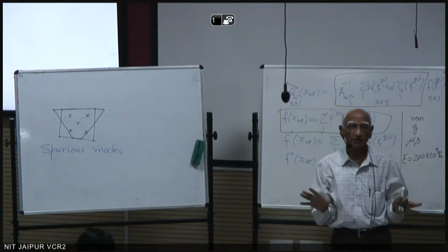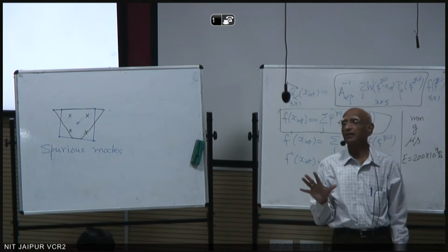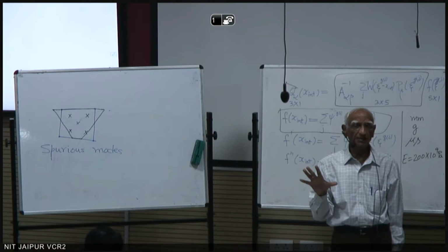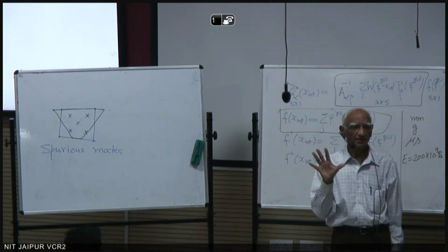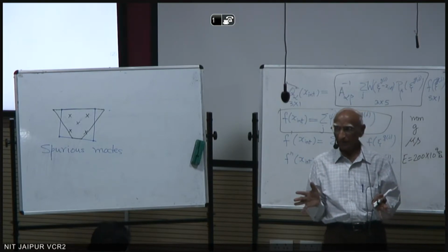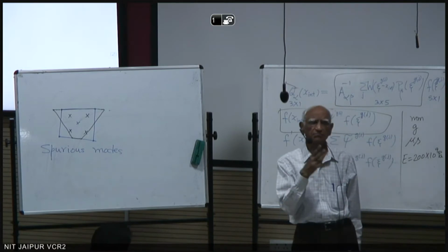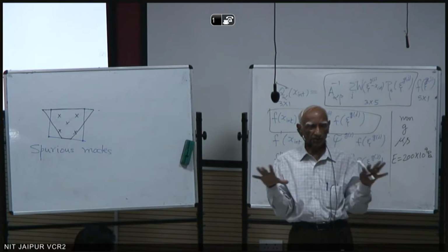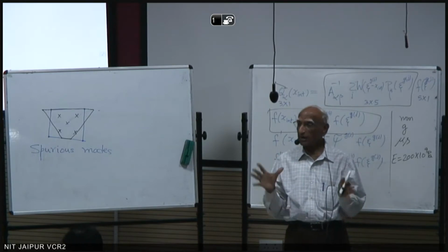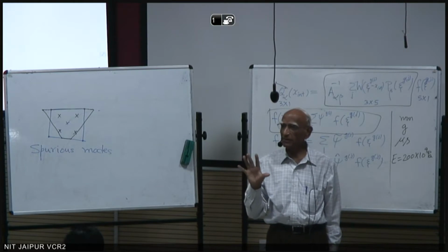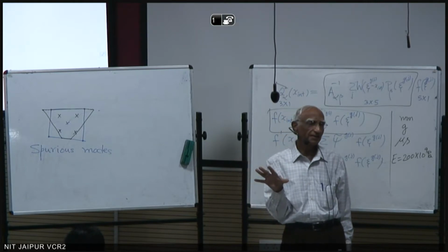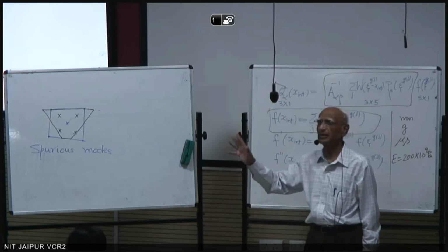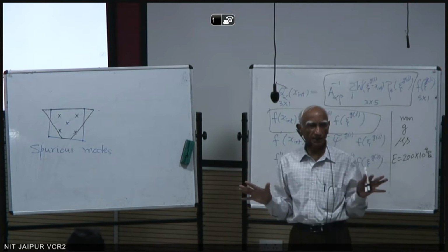There are spurious control algorithms implemented in different softwares. Like in LS-DYNA, there is more than one spurious control algorithm. So try a different one. Don't accept the default one. If you try a different one, then you will see that your answer will change.